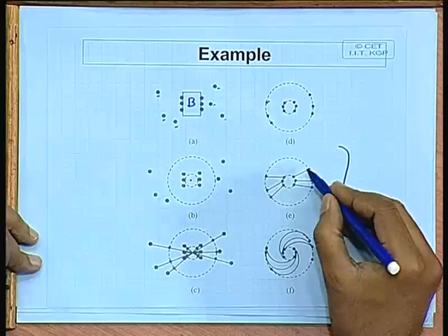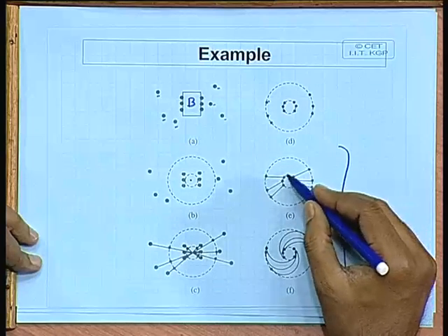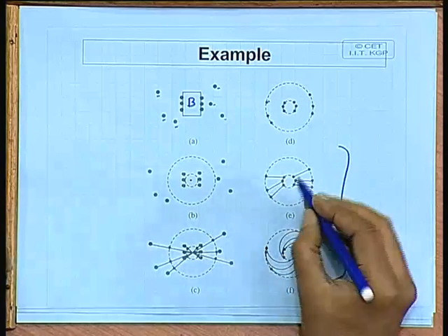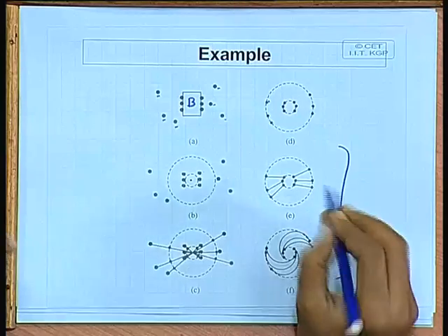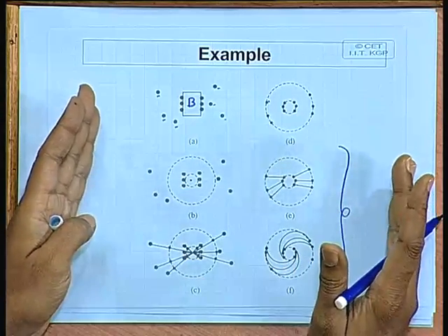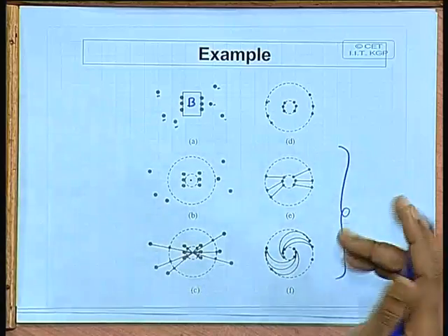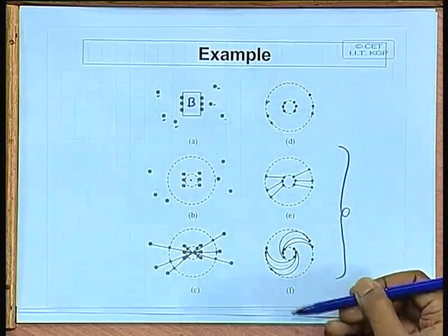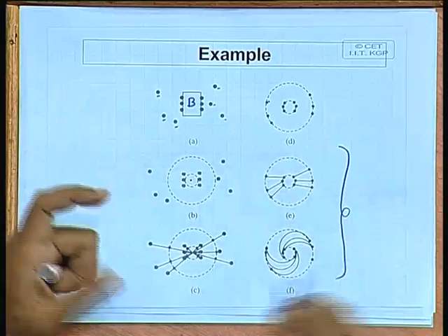And in this step also, if there is some concept of equipotential or functionally equivalent pins, you can swap them to reduce crossing. So, all these concepts are taken into account in this method. I am not going into the details of the implementation of the algorithm, but this is the concept. So it may happen that one pin in the inner circle is mapped to more than one pin in the outer circle. Yes, possible. So, this method is conceptually simple, and it tries to make a good assignment of the pins, so that during the routing the nets do not cross too much.